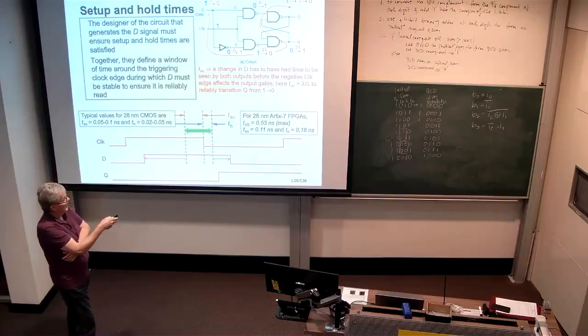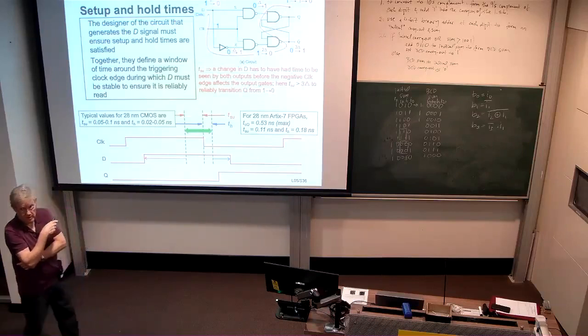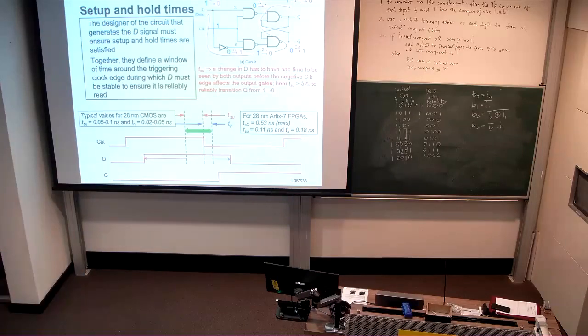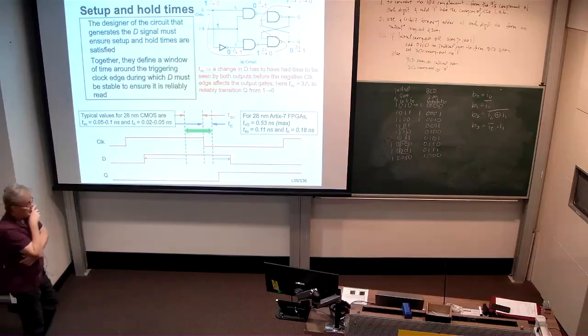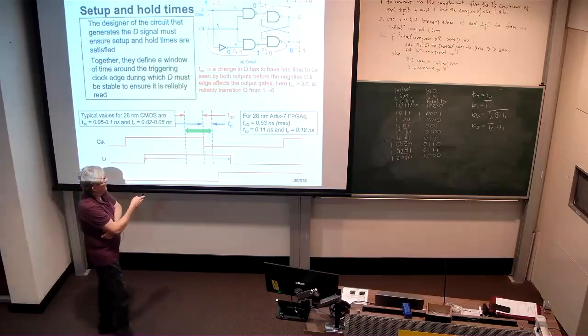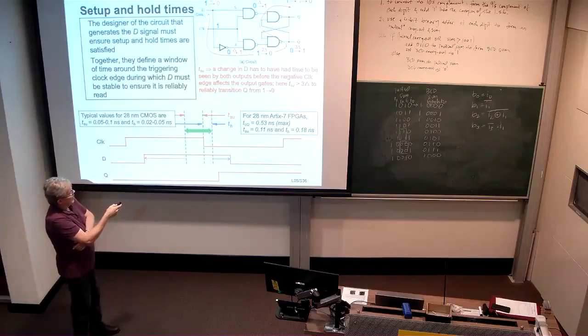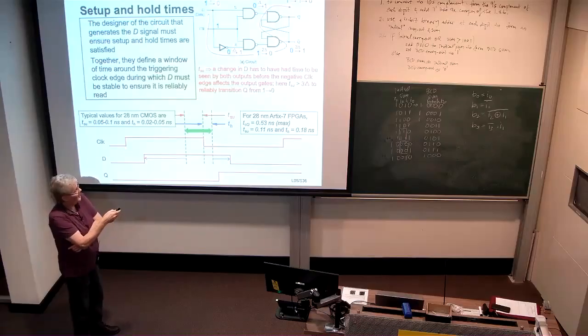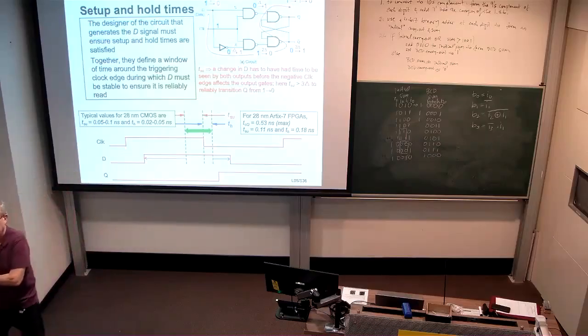Okay? And together with the 1 that we see on this wire now, we will see that the output of this NAND gate goes to 0 at 4 delta time. All good? All right. So we have to wait effectively 4 delta time for the output to even go to the right value here after the data signal changed.